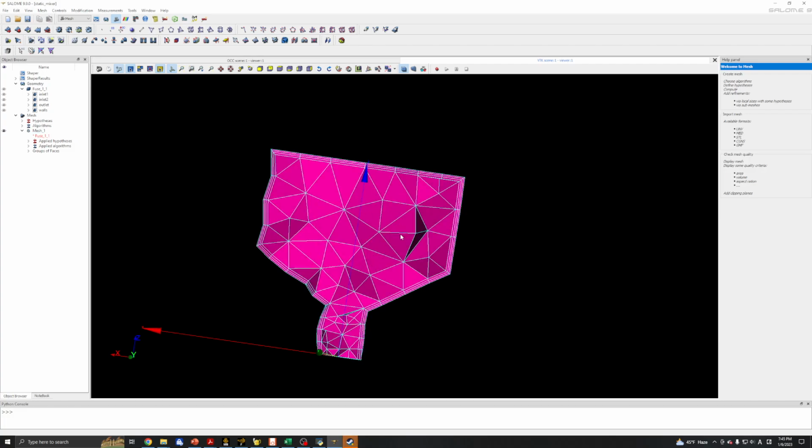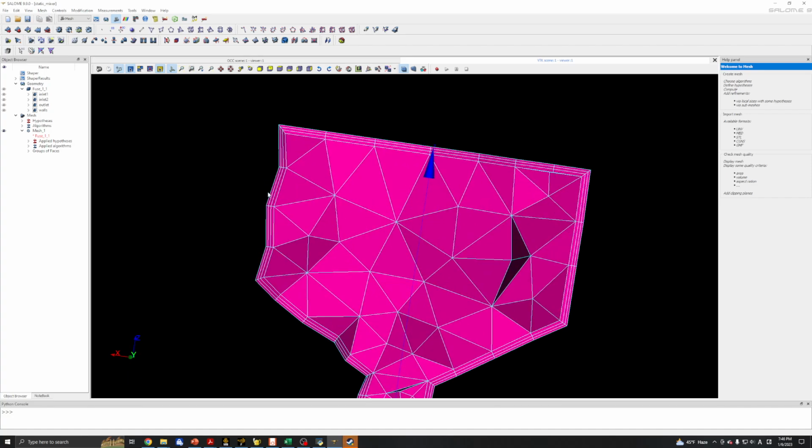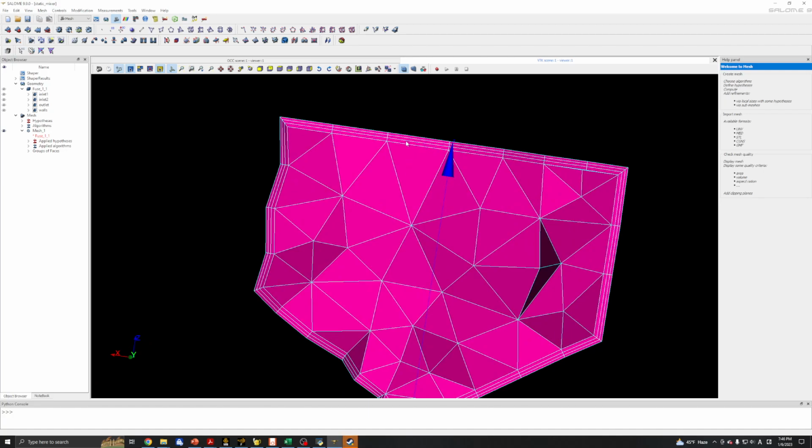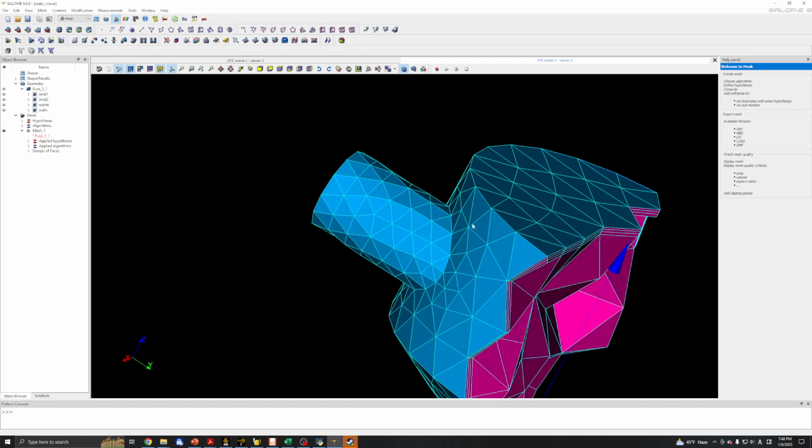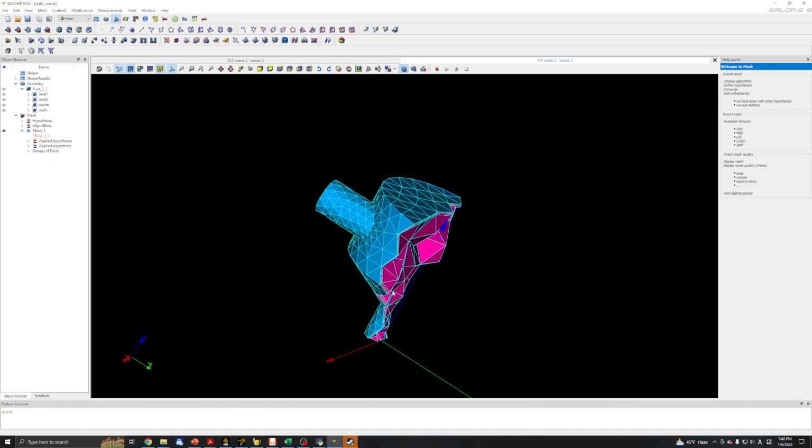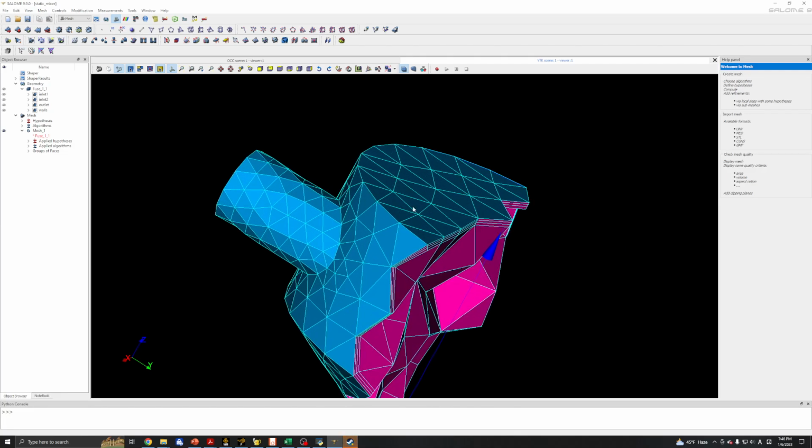Here the cells inside are very big, and the boundary layer mesh prisms are too thin compared to these. So we have a problem when calculating the gradients. So the trick is to use a new surface mesh to create the cells nearest to the walls, to make the cells nearest to the walls small.